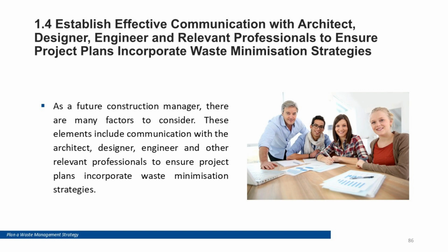Waste reduction works best when it is designed in, not added later. Effective communication with architects, designers, engineers, and key consultants helps embed waste minimisation into drawings, specifications, and schedules. It also helps coordinate material selections, standard dimensions, and buildability decisions that reduce offcuts and rework. Use clear documentation and consistent channels so changes are controlled and waste targets stay aligned with design intent and site delivery.